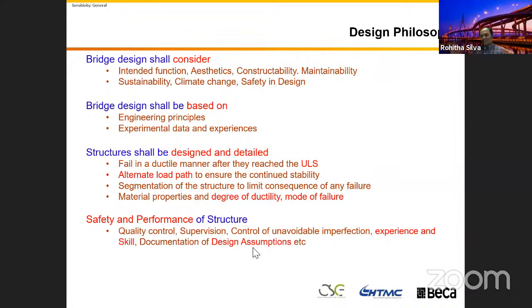If someone says everything is in the design drawing, that is not right, because you have to write down your assumption. If someone says, oh, the assumption is in the bridge design code, so then I designed this one, chartered engineer signed that one, drawing is there, that's the end of the story. That is not right. So you are liable with this one, because you need to make sure that the future generation can understand what you have done today. You need to have a proper design documentation to ensure that your design intent is documented.